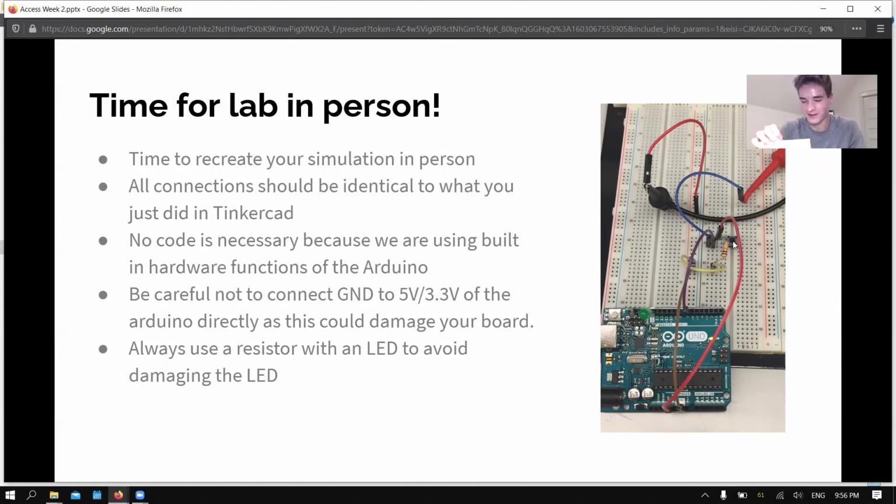Okay, so now we have just kind of the board components. Now we need to use the wires. So I'm taking a black wire, connecting that to the left terminal of the LED, and then that other side of the wire is going to go to the negative on the board, which is ground. And then I'll take a red wire and connect one side of it to the bottom right terminal of the push button, and then the other side of it to the positive on the board.